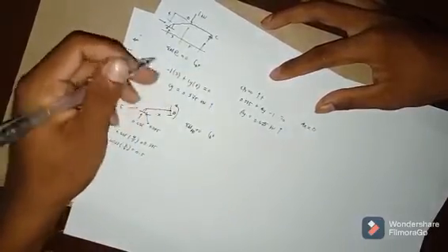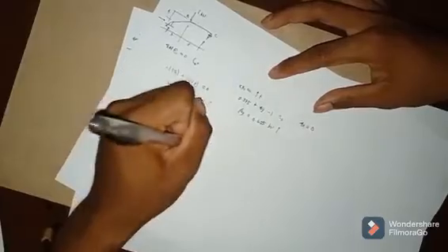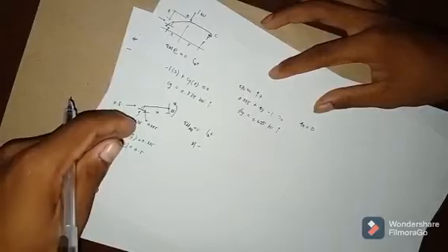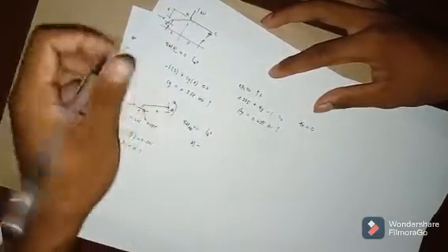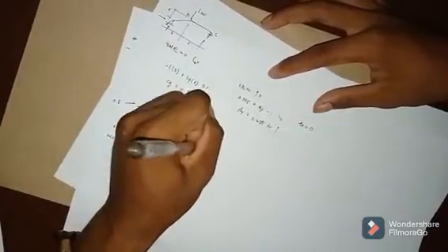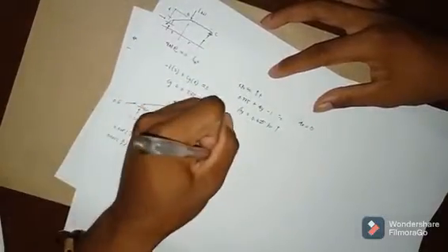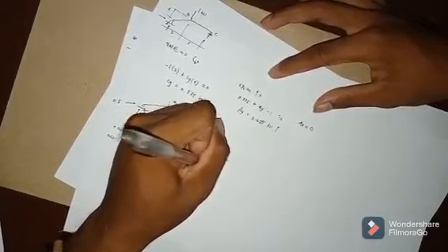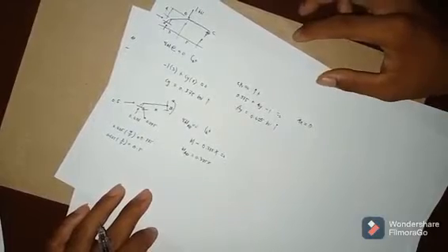So let's take the moment as positive moment times the X, and minus 0.375, rotating upward, so it is rotating clockwise, so negative, times the arm length, which is X, so equals 0. So moment AB is equal to 0.375x. So this is our moment at AB.